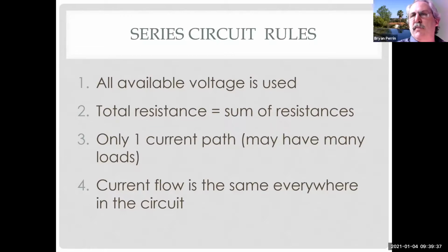I'm going to show you how to do a voltage drop test on the battery cable and show you exactly what's acceptable and how we do that. Yeah, you've got the right idea. You're going to put one voltmeter lead on the positive post of the battery and one on the positive post of the starter, and crank the engine over, because I can only use Ohm's law in a complete circuit, right? So I have to be flowing current through it. Then I can measure the amount of voltage drop. Thank you. Yeah, good thinking ahead.